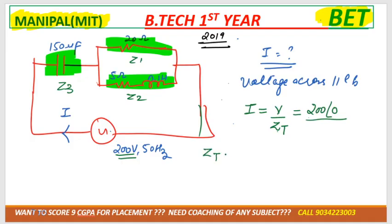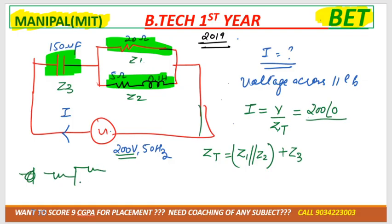So we can say that ZT is how much? As you can see that Z1 and Z2 are connected in parallel. So Z1 parallel Z2, and if I combine it, then that would be in the series combination with Z3, correct? If there was a resistor here, and if we need to solve the complete total resistance, what we'll do is, R1 and R2 are in parallel, then we'll combine it. It is in series with R3, correct?